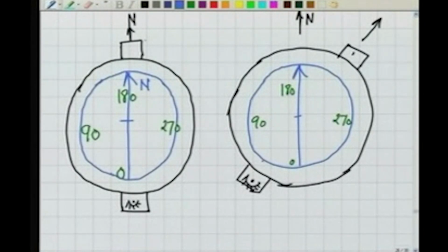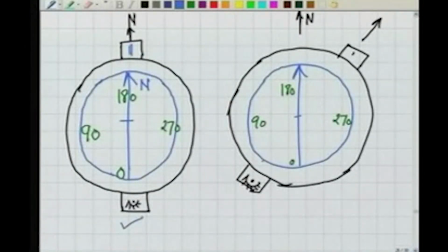Right now, for example, the prismatic compass is kept in such a way that this is the eye vane, the object vane, where a little twine or thread, a wire, is there. This is the direction of north. All these are aligned. So our needle, that's the blue line here, having N here, will be suspended in the direction of the north. So the direction of north is here.